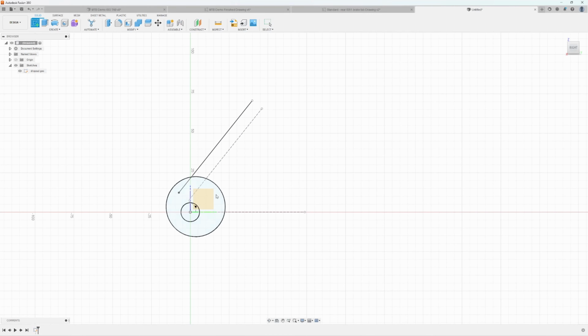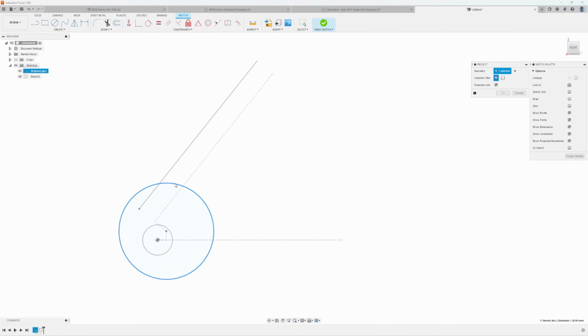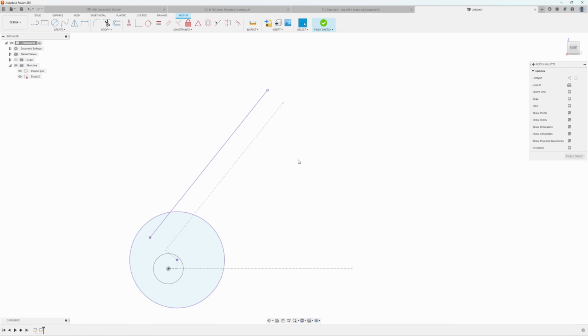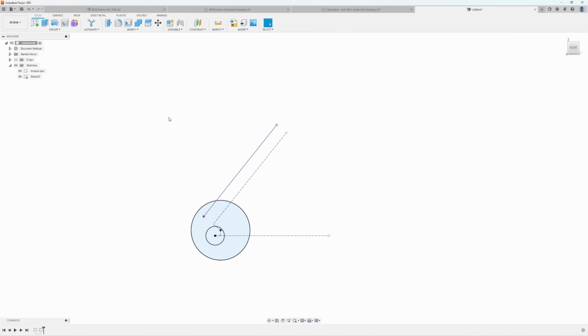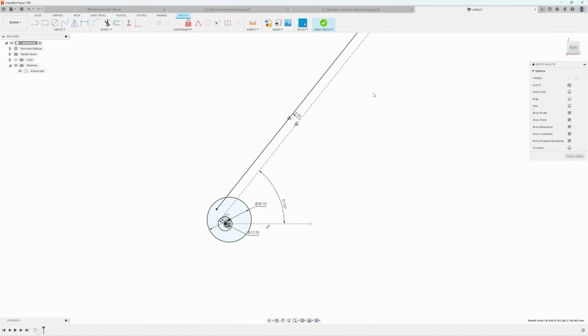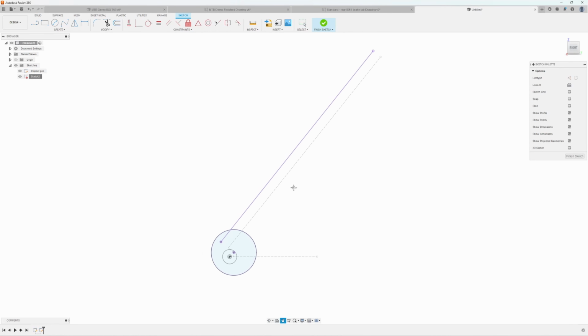And I'm going to create a new sketch on top of that. And now I can draw my ISO tab. So I'll project this geometry because I want it to touch this dropout. And I want to project this geometry because I want the tab to touch the seat stay. Just really quick, I realized that this line probably needs to be longer. This is just a construction line, it's a rough sketch. Go back into here and edit this. All right, so now I have those features.